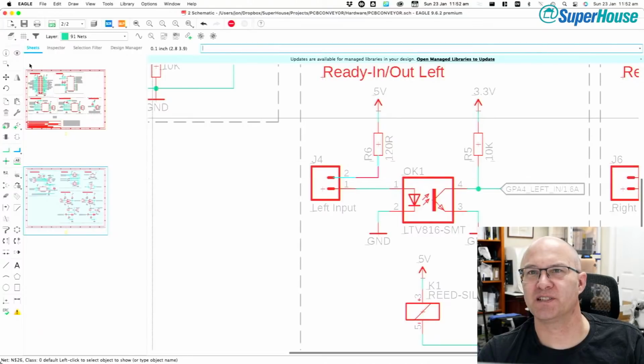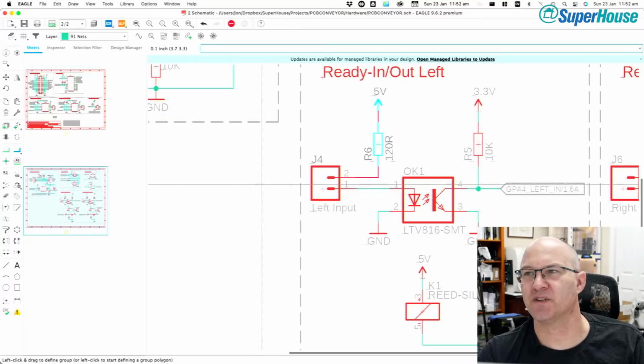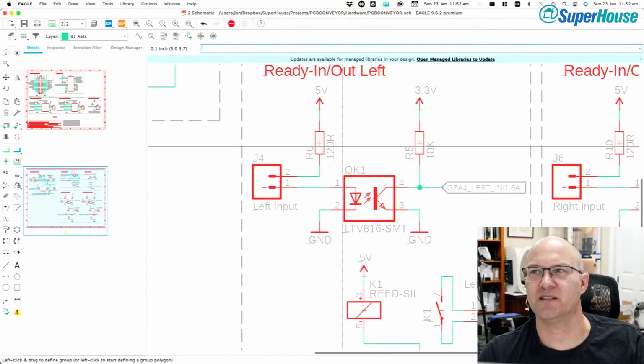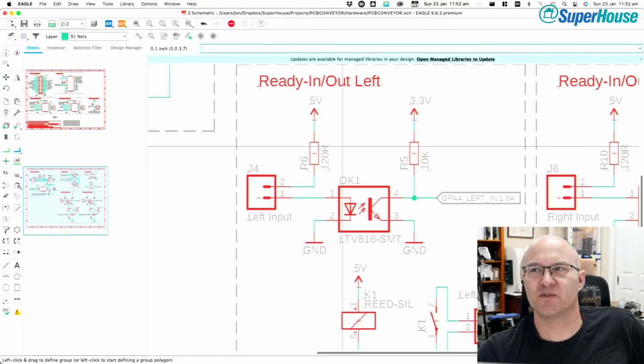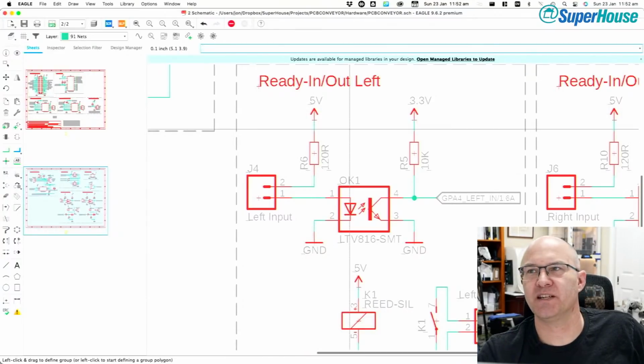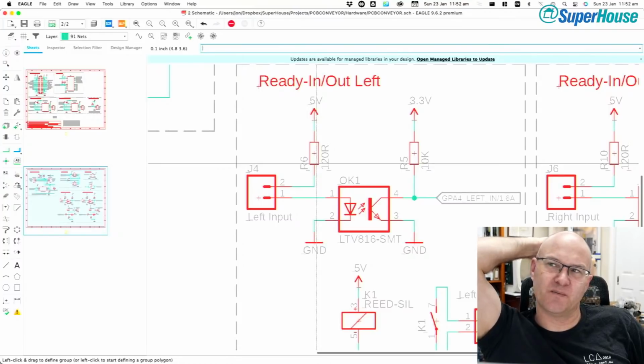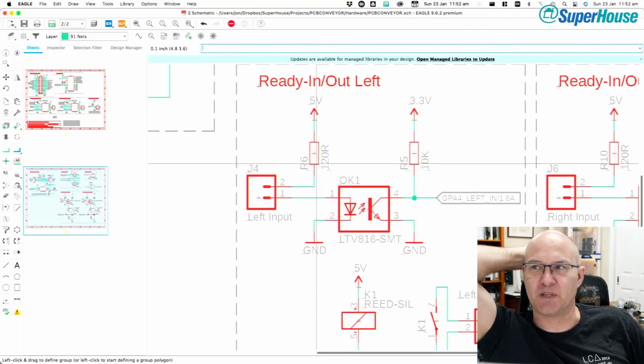So if there is noise being induced in on this wire, it could feed back through this 120 ohm resistor and affect the 5 volt rail, which is kind of not ideal. So if we were making this really ruggedized, what we would do is have a dedicated voltage regulator that is feeding the rail for these inputs. But that is another step again beyond.